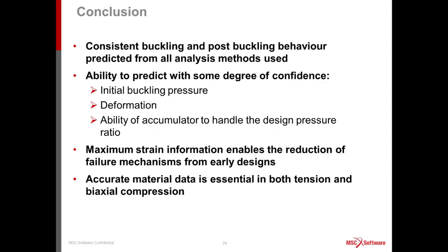The maximum strain information that we achieve from the software enables us to reduce the failure mechanisms from a very early stage, allowing us to tweak how the molds are designed to ensure that we don't pick up a high stress point at a mold split line. However, it's very, very important that your material data is from both tension and biaxial compression state, as they're both equally important in terms of the simulation result.